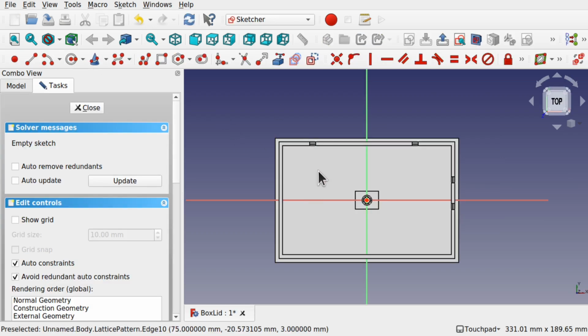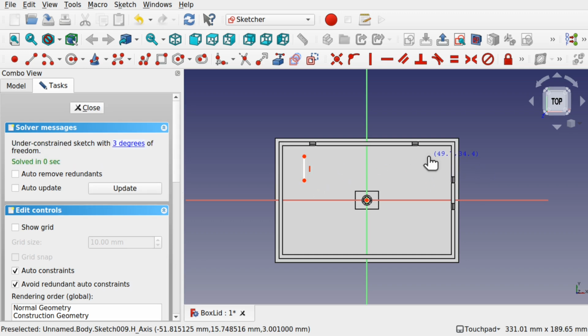New sketch. And we can start adding the geometry to actually place this in those different points. I'm going to use a line. Now the reason why some people use the L shape is because you can see it as an axis, basically the X that runs through the kite and the Y that goes along here. Remember the Z is this point here that runs towards us, and this will be the point of origin. You can use lines like this, but make sure that the lines run in the same direction. So run those two this way.